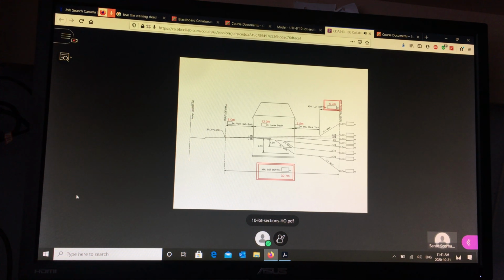The maximum allowable slope is 5%. If you use 5% to design your side yard, right, the side of the lot, the edge of the lot, the side yard, you're going to cause problems internal to the property. Okay, and we're going to do some math together. I'm going to show you exactly why. I'm going to do a sketch up to the side here. I'm going to zoom down near the bottom left. I'm going to draw a house and I'm going to draw a lot and a house. So I'm going to do this here. Here's the lot. This is the plan view, and then I'm going to draw a house.